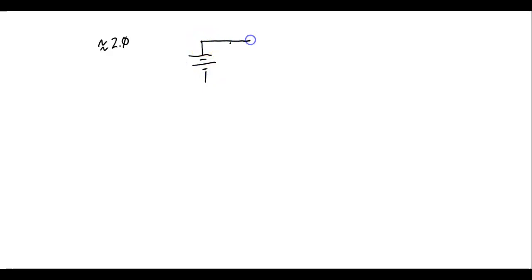Yeah, 450 millivolts. And now we're going to have to put a resistor on this thing because as soon as it cuts on, anything above VF is going to act like a short circuit, right? Understand? And what size are we using there? We're using a 330 ohm. And then we're putting our diode in forward biased.